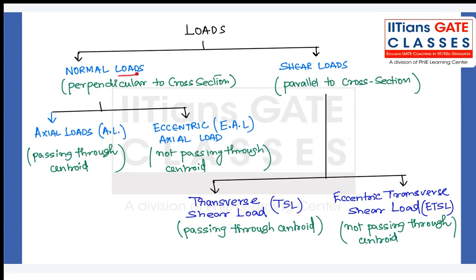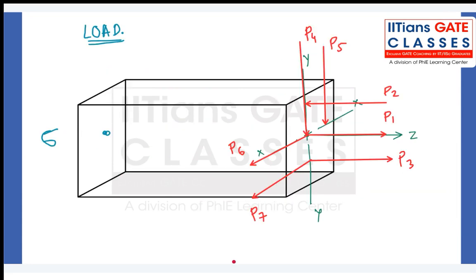Right? Mind you, these are not stresses. These are loads. I'm talking about loads. Can you look at this diagram and tell me which of the following 7 forces are normal loads? Normal loads are those loads which are perpendicular to the cross section. Can you look at the cross section? Can you look at these loads and tell me which of them are normal loads?